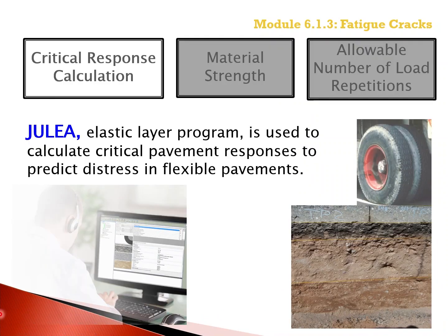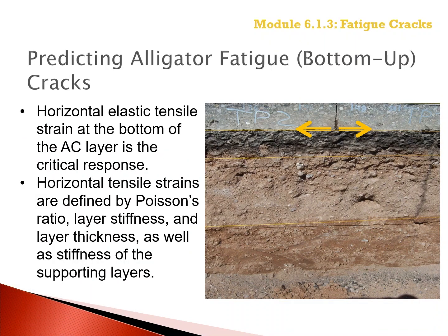As previously noted earlier in this module, Module 6, as well as in Module 2, Julia is an elastic layer program that the Pavement ME design software uses to compute the critical pavement responses. Julia is used to calculate the critical pavement responses for predicting bottom-up fatigue cracking.